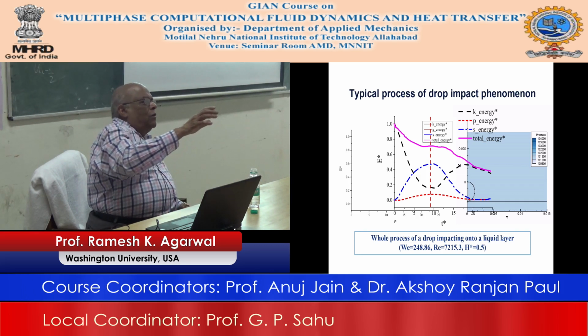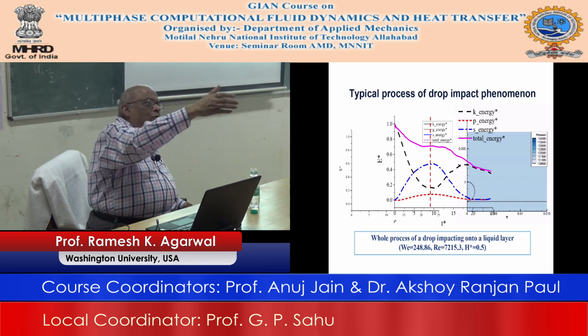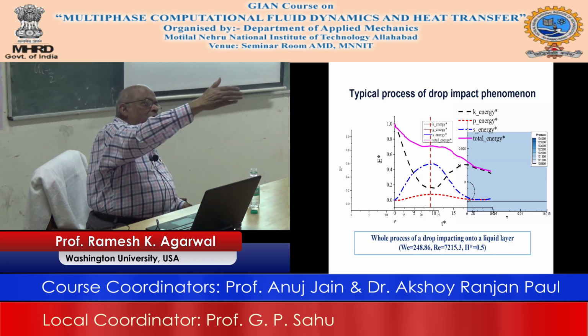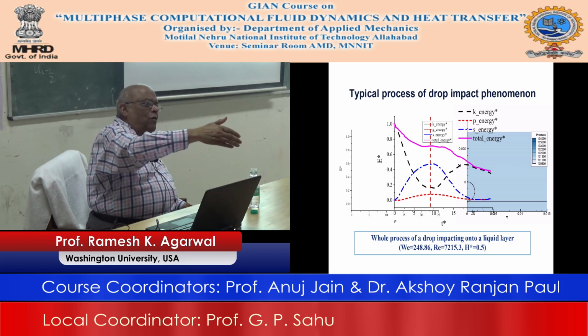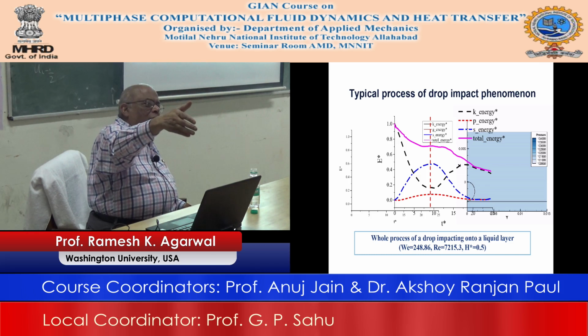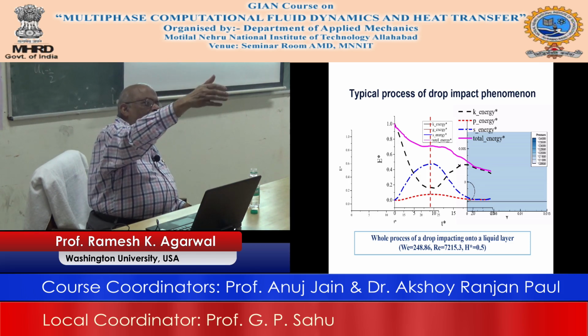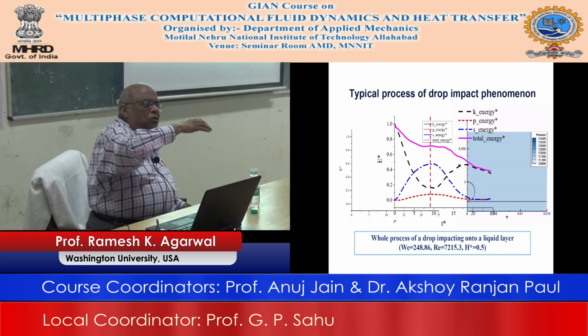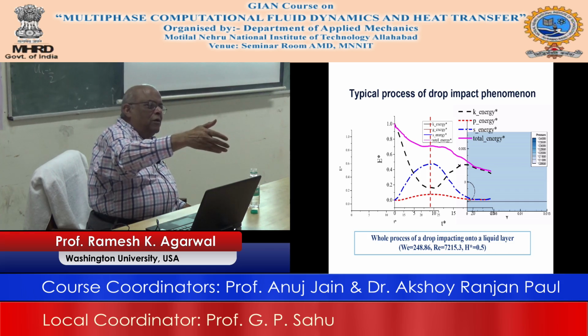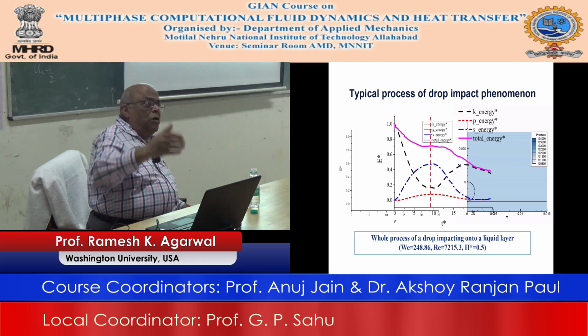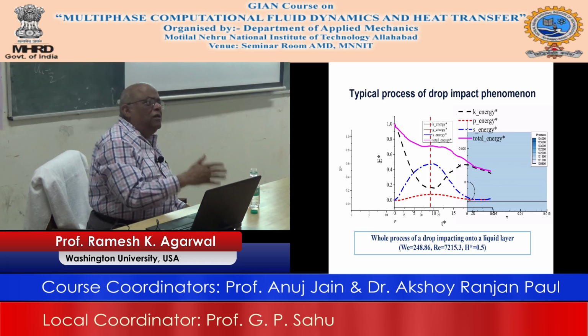Listen. Now what do you do? You apply the upstream boundary condition as a uniform velocity, and a pressure outlet boundary condition. At the top you can have pressure outlet or whatever boundary condition. The solid surface is an oscillating boundary condition, but the entire computational domain is empty. There is nothing there.